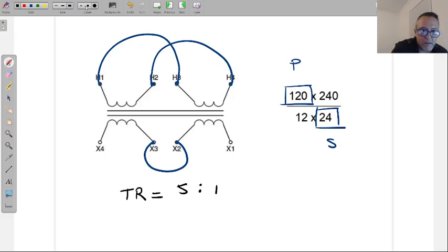All right, this is important that you understand this part because this is the part that sometimes lands confusing. When you set up this transformer with parallel on the primary and series on the secondary, you're not really setting up a transformer that has to receive 120 and is going to produce 24 volts.